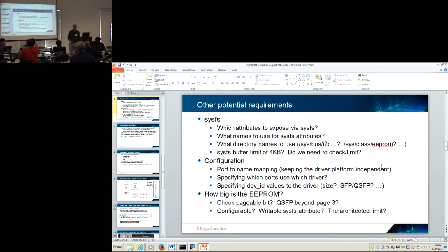But then in the sysfs, under that same class where the EEPROM file is, you can have another attribute file where you can describe what this EEPROM has, right? Yes. That's one way of doing it. There's a page file which is say 5 or 10, right? Yes. Then you can negotiate the application. You can negotiate that number and then come up with, okay, now I can access page 5.